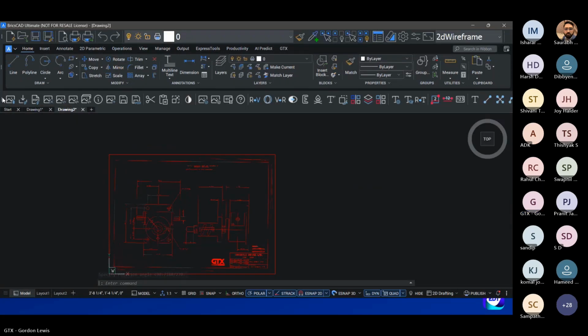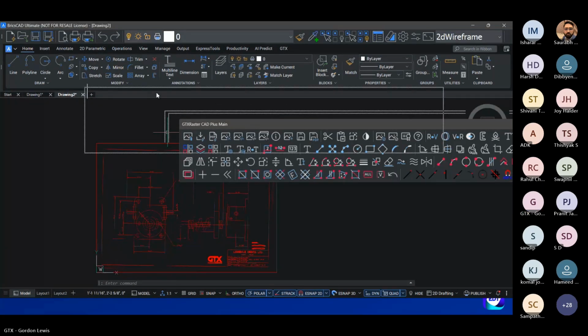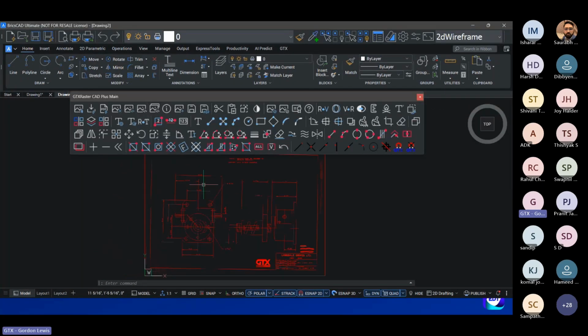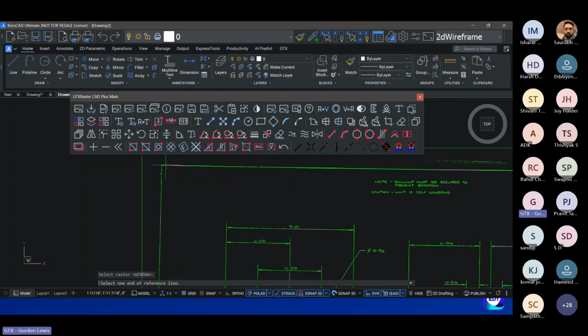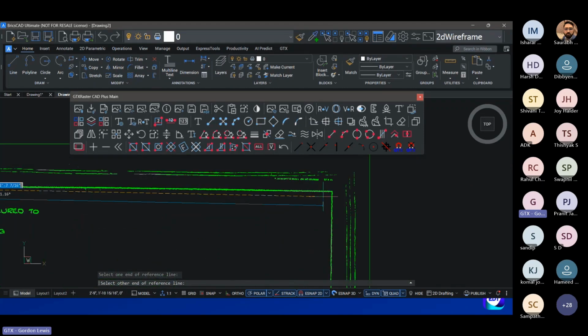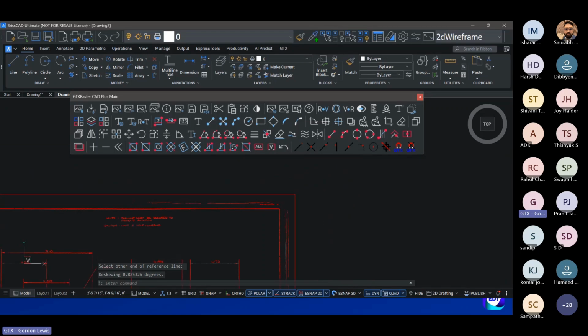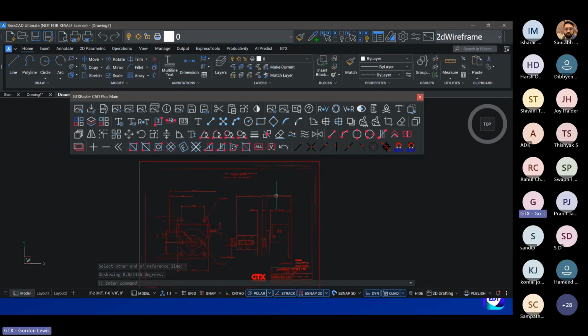Oops, sorry. So now the image is turned 90 degrees. You can see that the image isn't quite square within the drawing frame. So what I want to do is deskew it. I pick all of the data. It says keep selecting. When I don't, everything's gone green. It then says give me a reference line. It could be the line along the edge of the drawing border, or it could be a center line within the drawing. So I've now deskewed the image.